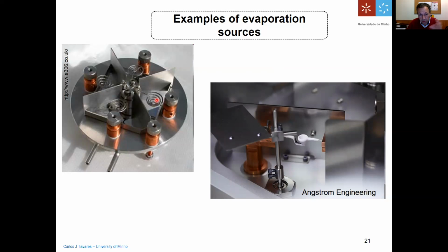And these baskets are normally used once, twice, 3 times, and then the filaments will become very brittle and they can break very easily. So you never use them more than 3 times. So this is my general rule of thumb. And you certainly do not use it with different materials, because then you'll have cross-contamination between chemical species, okay?